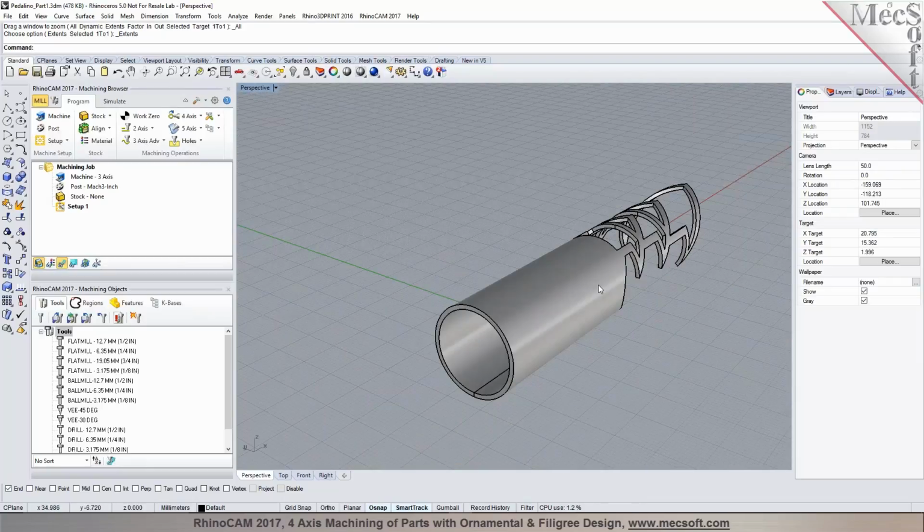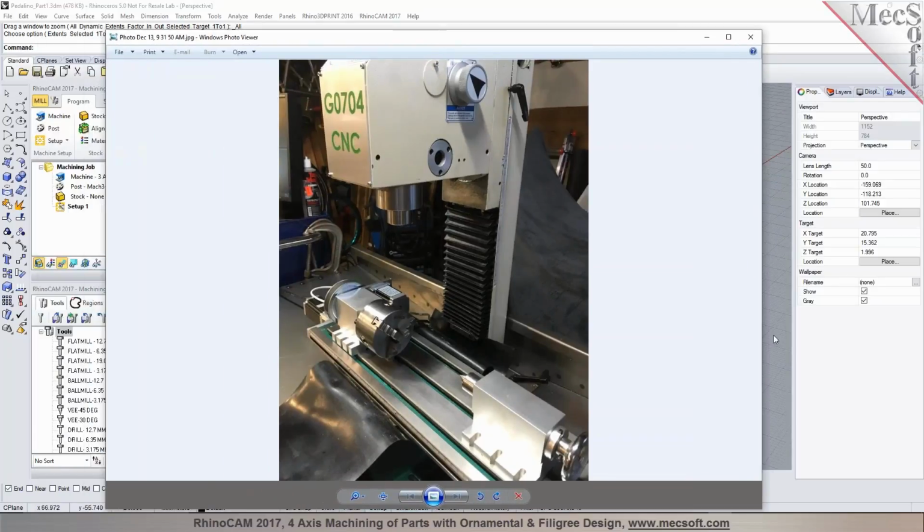So both the parts what you have requires to be machined on a rotary chuck, or what we call as a 4-axis machining process. Now, if I take a look at the picture of the machine tool that you've sent us here, your rotational axis, based on what I'm seeing, could be either X or Y, but most likely it looks like this is your X-axis. Correct me if I'm wrong. Yeah, that's correct. Okay, perfect.